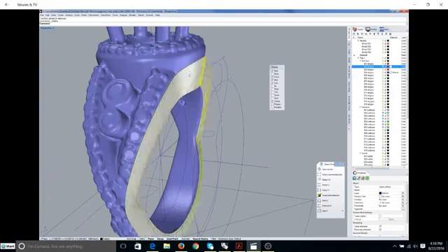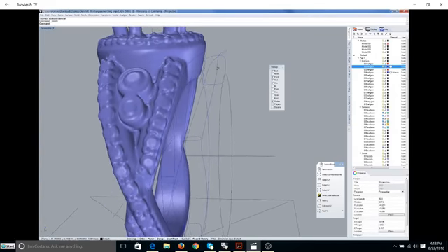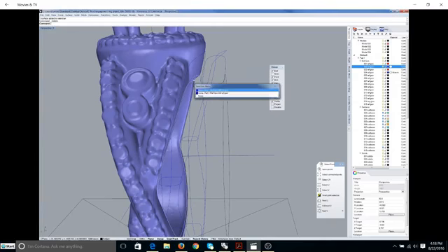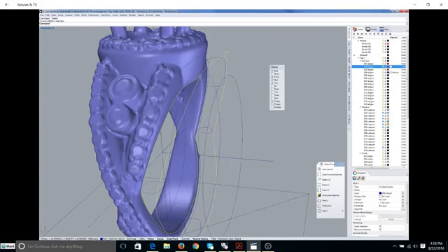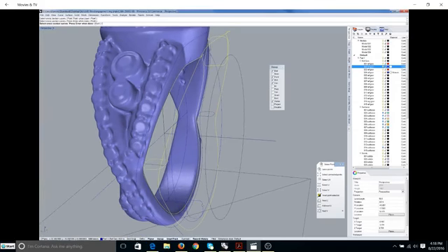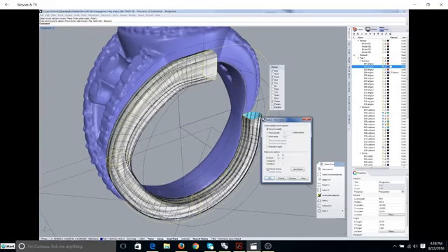So I'll just get rid of that. Another way I did this was I used two paths, this one and this one, or two rails, and I will go in here now and just grab these cross sections, which is another way of doing this. And we want to close sweep, say OK.